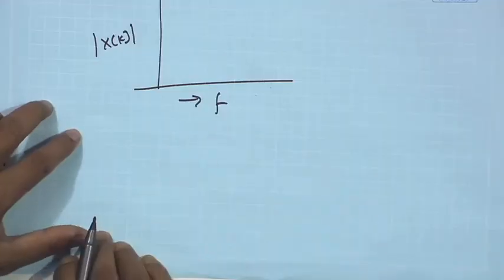Suppose I tell you to record a signal, design an algorithm, and compute or draw the frequency response or spectrum of the signal. I am not saying spectrogram. The amplitude response representation is called the spectrum. It is nothing but the mod of X[k] versus frequency.